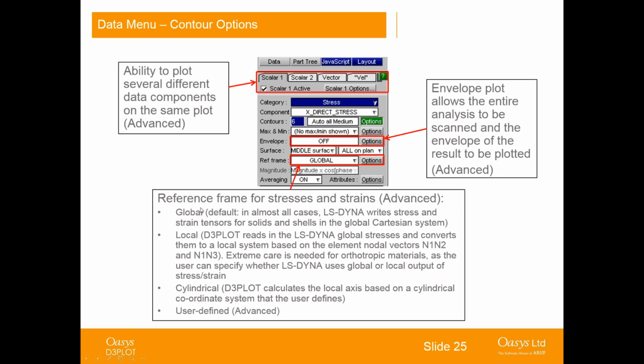And some of the more advanced features are that we can choose to change the frame of reference for the stresses and strains. So we can choose to have either global, local, or different coordinate systems. Okay.